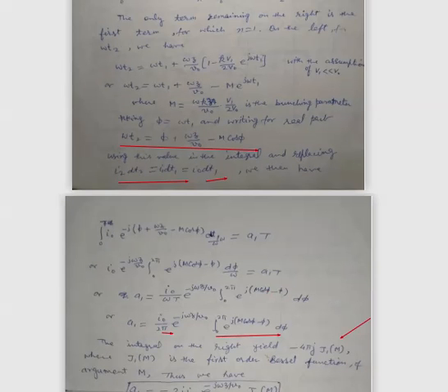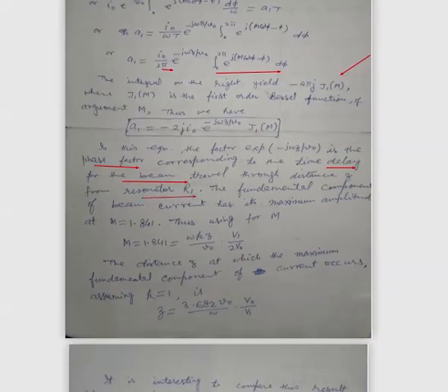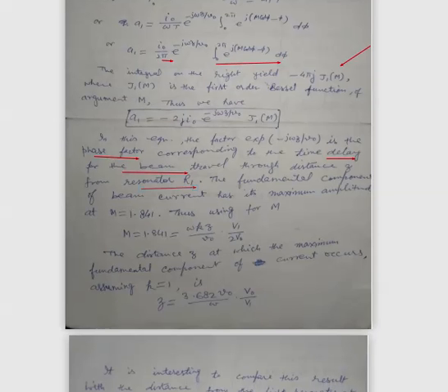The fundamental component of the beam current is thus obtained. Later we will use this equation to find out the power output and the efficiency of the Klystron. Now considering m equal to 1.841 value, for which the Bessel function J1(m) will have its maximum value.